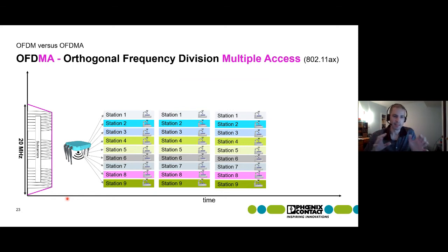These communication points take microseconds to get on and off the spectrum. But if you have a high density of devices, access points beaconing down, devices trying to send data up, and other devices trying to join the network, all of that is time on the air where other devices can't send data. Now these stations divvy up the spectrum and can talk simultaneously.